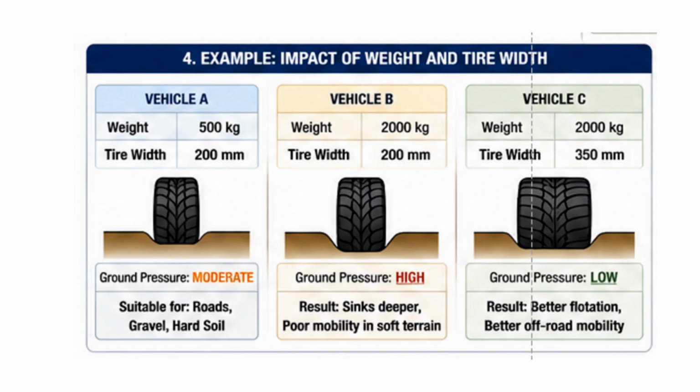The greater load is now applied over a similar contact area, so ground pressure becomes much higher. As a result, the tyre sinks deeper and mobility on soft terrain is reduced.